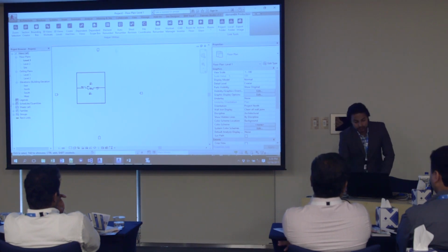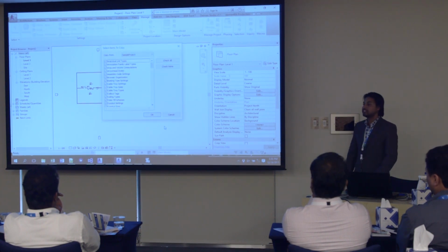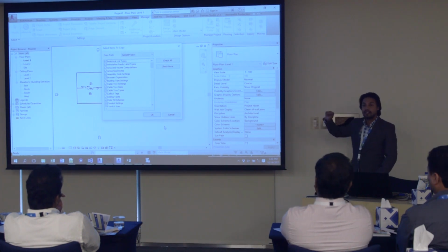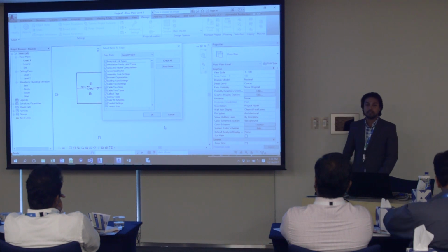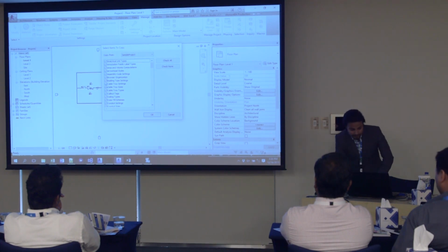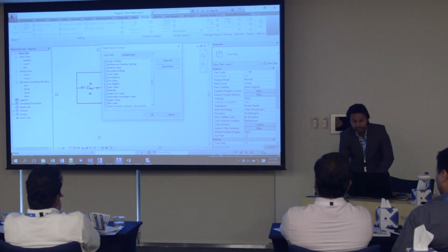The big problem was that one of my new colleagues transferred the project standards, and there is a parameter there that actually overrides the coordinates of the project. What was that parameter? Anyone? Any guess? Project info. Project info is the one. So as a tip, whenever you open Transfer Project Standards, make sure you say Check None first.